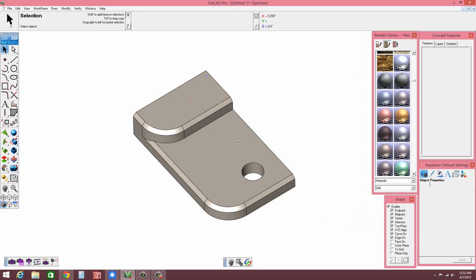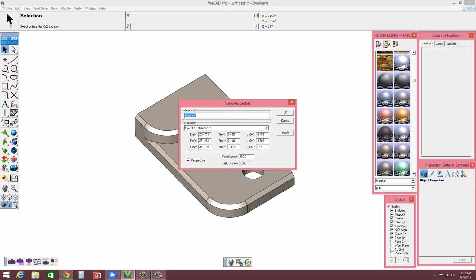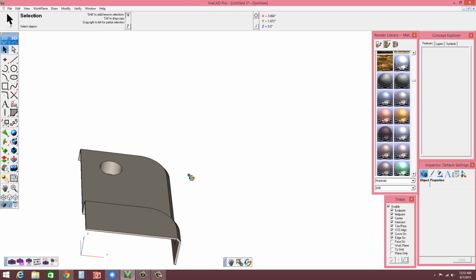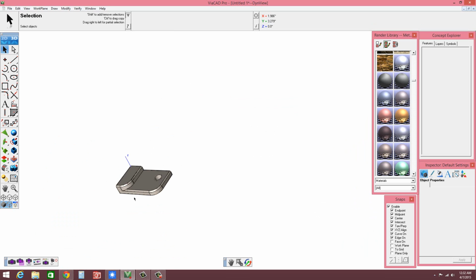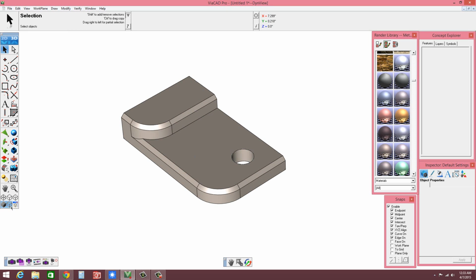Now, when you want to photorealistically render this, one thing you might want to do is first set up this little tool over here for perspective. That gives a vanishing point. If you go to this one, it allows you to adjust the focal length or vanishing point. Let's change it to 100. Okay, we're getting some weird things occurring there. Let's change it a little bit. Maybe we'll change it to 50. All right, and then get it to the orientation that you would prefer.